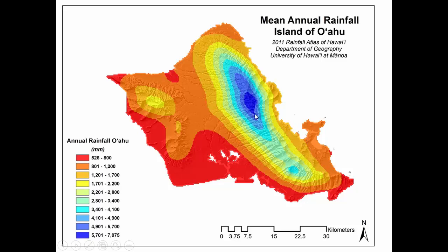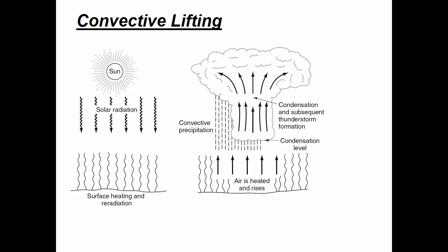So the effect that you see here, you can kind of tell from the shading that the mountains are here, and so the rainfall is coinciding with the mountains, and then the flat parts of the island are where it's not raining as much because there isn't any lifting that occurs. So orography is the second effect. The first one was convergence or frontal lifting. The second one is orography, which you can think of as an obstacle that's forcing the air up to cool, to oversaturate.